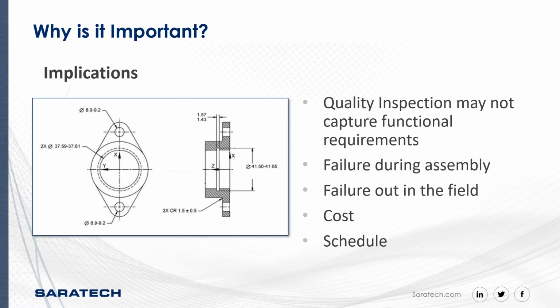Likewise, the thicknesses might be correct in certain places they are measured, but if the flatness of this section here has some sort of lobe here, it's now introducing different loads that probably weren't accounted for. So again, this is introducing risk into your part that you can probably get away with for some time, but eventually, if it goes unchecked, it'll come to bite you.